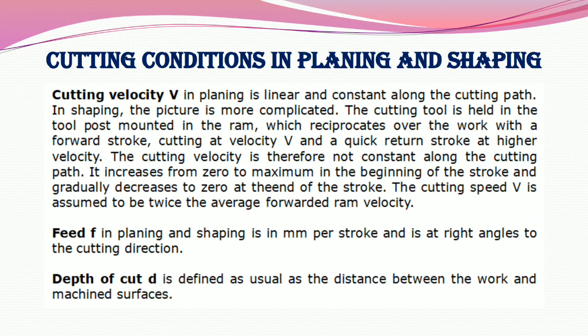Feed f. Feed in planing and shaping is in millimeter per stroke and is at right angles to the cutting direction. Depth of cut d. Depth of cut is defined as usual as the distance between the work and machined surface.